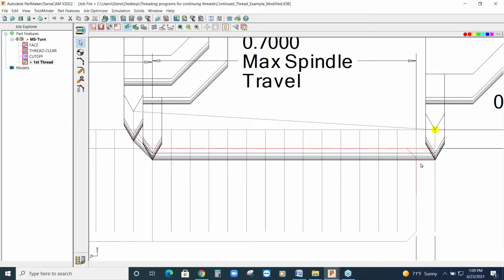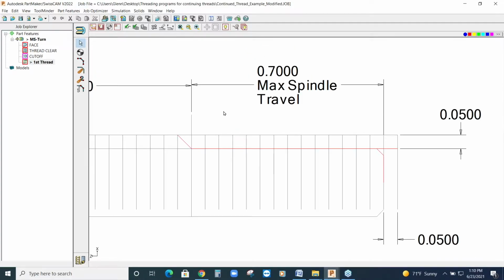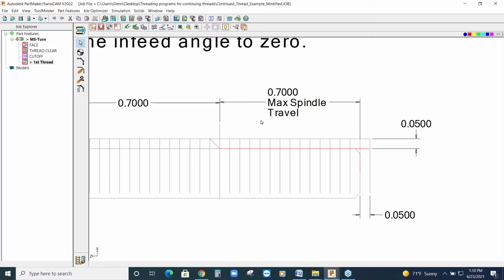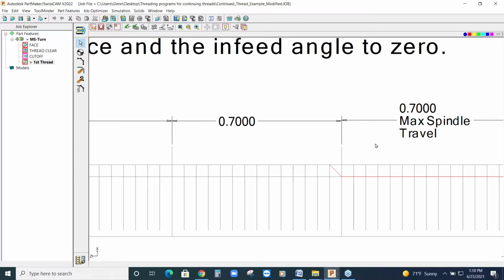So it's feeding in the 1 pitch amount and feeding out on the pitch. Well, now I need to make the second thread, so I'm going to make a new color for that one. Let's go with dark blue, and pan that over. So now my second thread, I need to start at this point. That's 1 pitch away, feed down the 1 pitch, come over and out again.